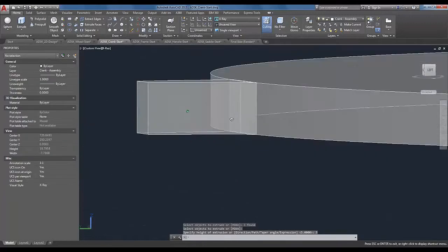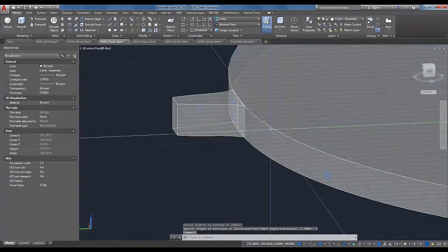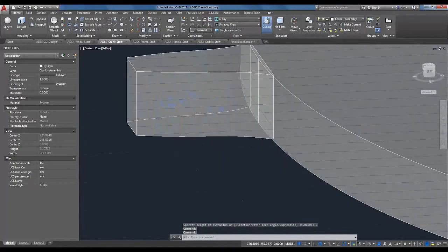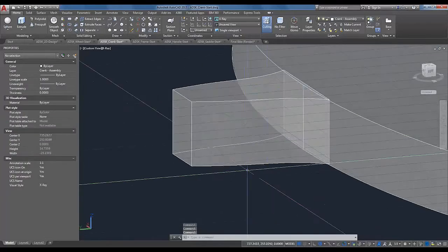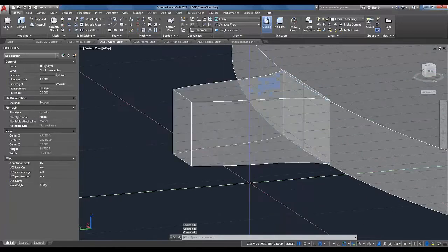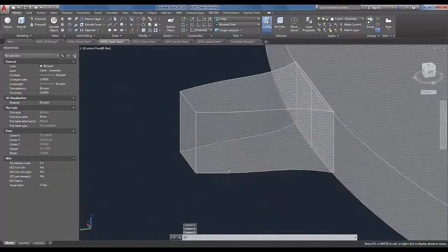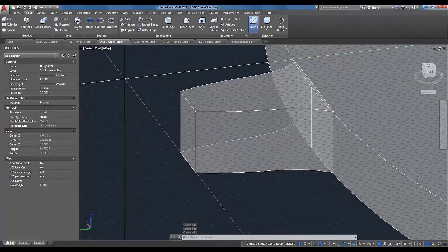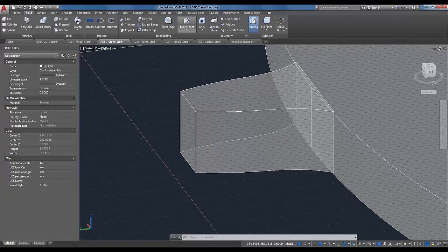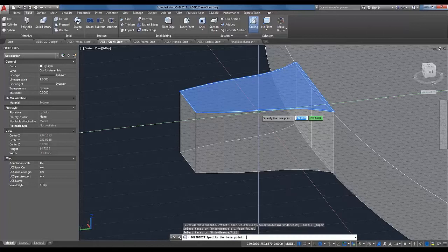So you can see how the tooth and outer circle are coupled. But this is not really representative of an actual gear tooth if you've ever taken a look at one. They have these tapered sides on either end. Not to the degree of the front and back, but they do taper. If I go to the Solid tab, see this taper face? I'm going to select that, and holding down the Control button, select this face, hit enter.